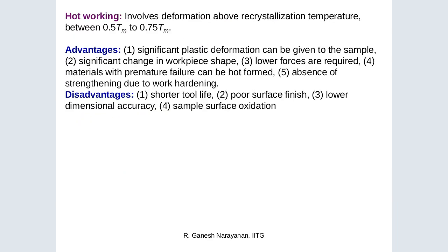What about the hot working environment? Hot working involves deformation above the recrystallization temperature, between 0.5 and 0.75 of the melting point. Advantages: number one, significant plastic deformation can be given to the sample.